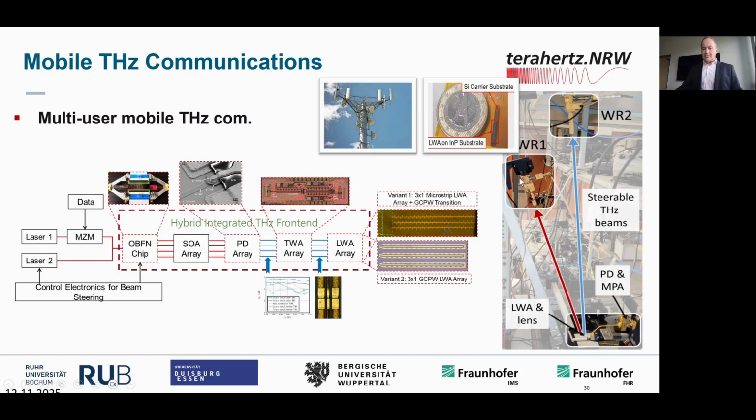As I mentioned, in this test we did it only for 2 beams, and we were able to carry up to 30 gigabit per second on a single beam with this technology. This is further explained in the next coming up video. Again, it shows you a little bit of explanation how we are using this frequency steerable antenna. It's called leaky wave antenna. Just have a look.